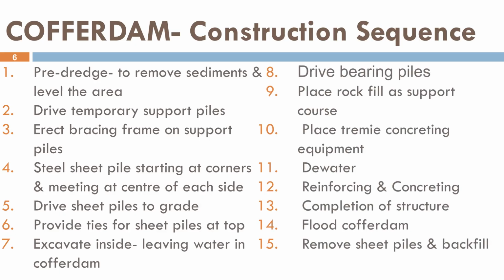Bearing piles are installed, followed by a rock fill layer and underwater placement of tremie concrete. Water is then pumped out, reinforcement is fixed, and the permanent concrete foundation is constructed. After the foundation gains strength, the cofferdam is flooded, sheet piles are removed, and the area is backfilled, ensuring safe and stable construction.